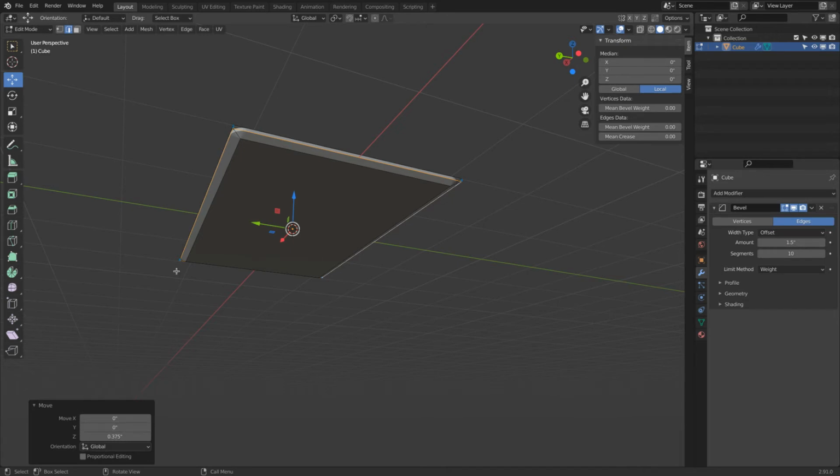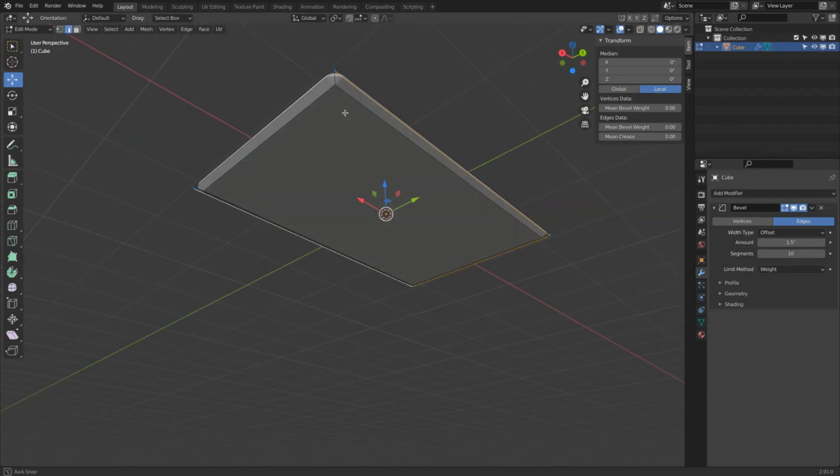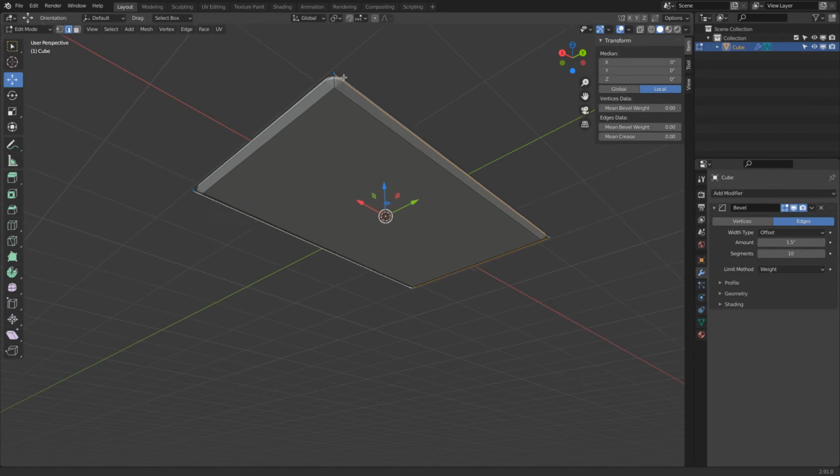One note about this. The moment I click an edge, for example, I'm doing another command. I'm doing a select command. And you see this toolbox is gone. So I cannot later go back and select all these edges and then modify where I move them to via the value. So every command we do gets this dialog box to modify the properties, but once we then go to the next command, we can never go back and modify the previous command values.